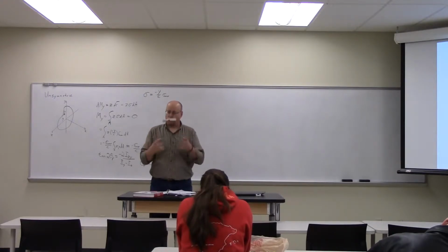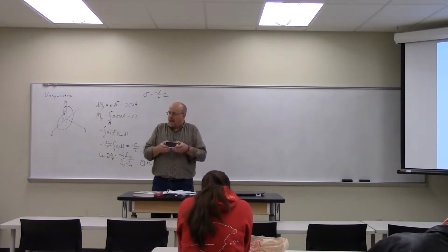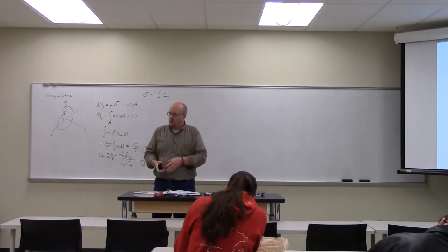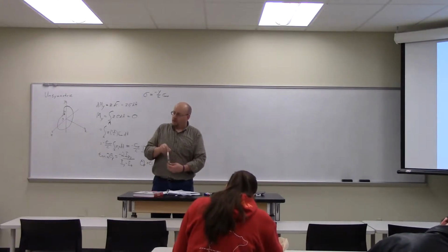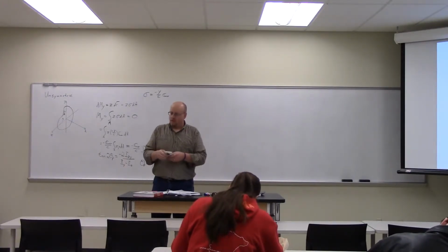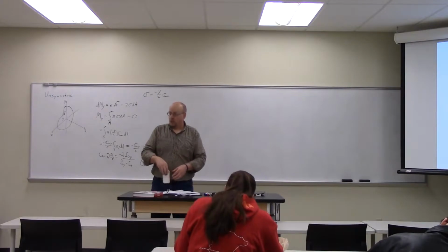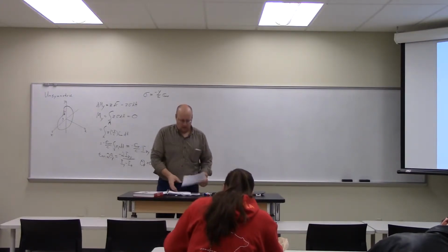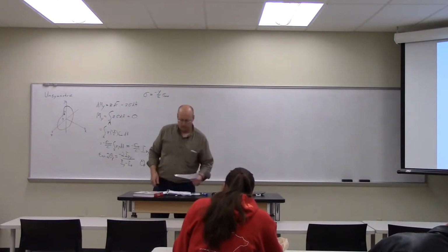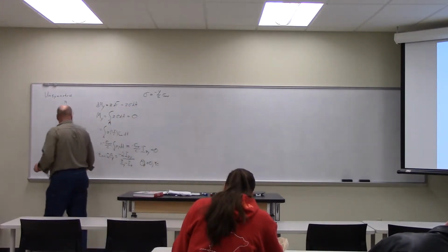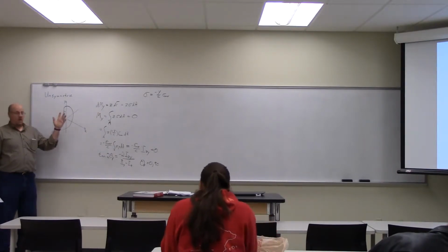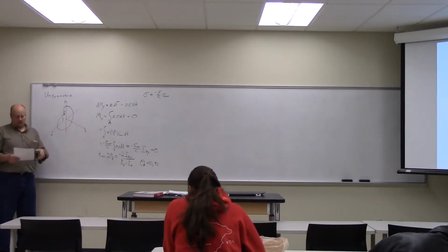This is the smallest moment of inertia. This is the minimum moment of inertia, because this is the point where the mass is the closest to the center of rotation. Here, maximum inertia, the mass is the furthest from the center of rotation. In between, it's in between, and that's why we don't get good stable rotation there. There can only be one max and one min. Anything else creates instability. So if it's equal to 0, then we're at a principal axis. If it's not equal to 0, then we're not at a principal axis, and we'd have to move.